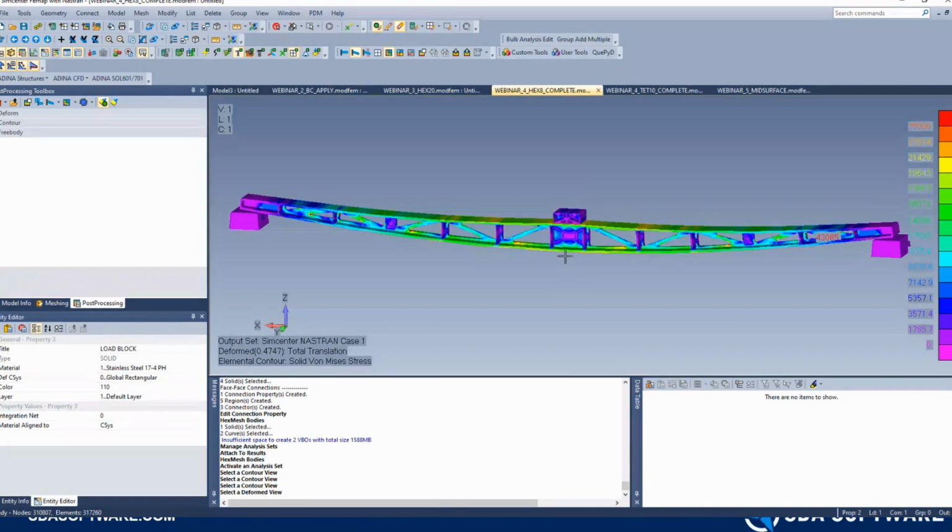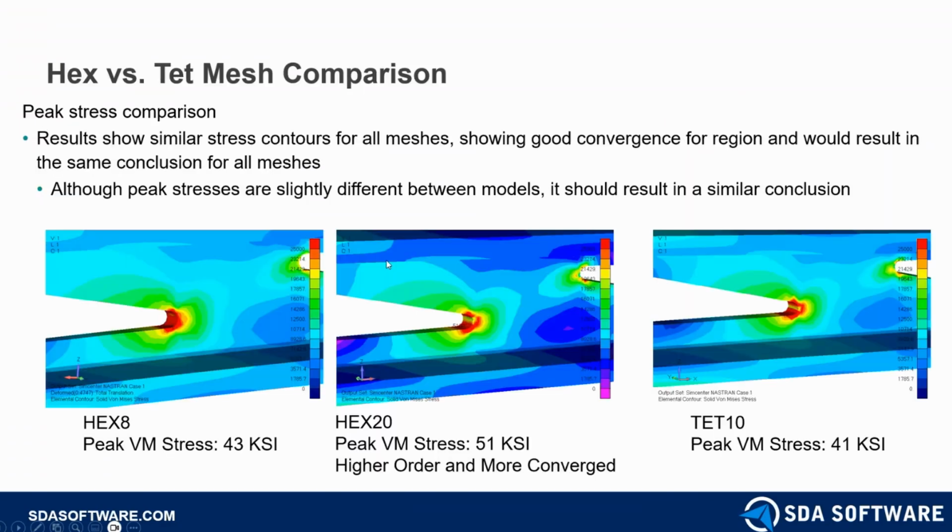So we've shown a little bit of the control of the post-processing side. We're going to show some more of this very shortly, and some of the other capabilities we have with this model as well. Now, how do all these models compare specifically on stress and also runtime? So first of all, for stress, we're actually showing very similar numbers between the TET 10 and Hex 8.